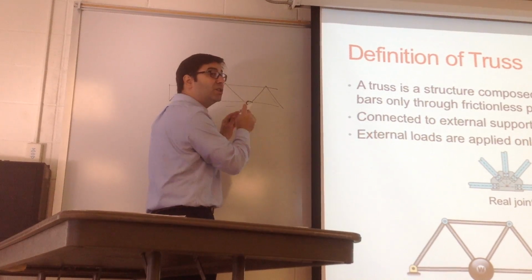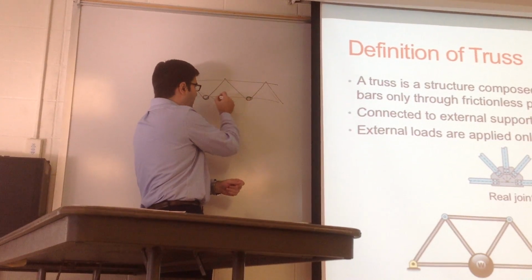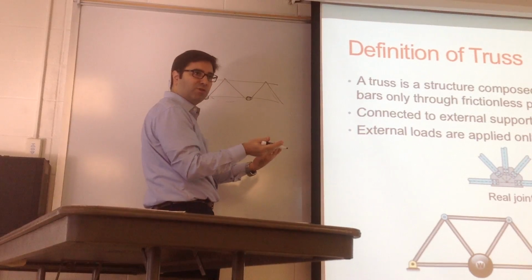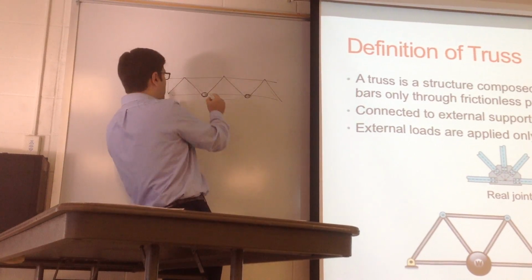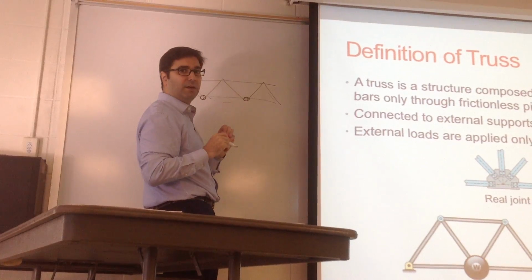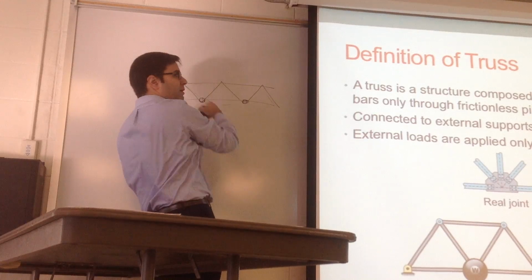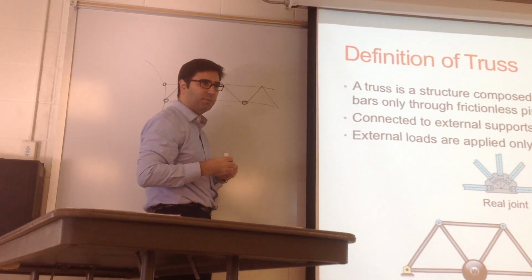Okay, so this is not designed for carrying load at the center point. It's always designed for carrying loads at the end points. The same for the supports. If we want to attach this to the wing, we're going to put support points here and here. And here you will have the fuselage structure, for example.